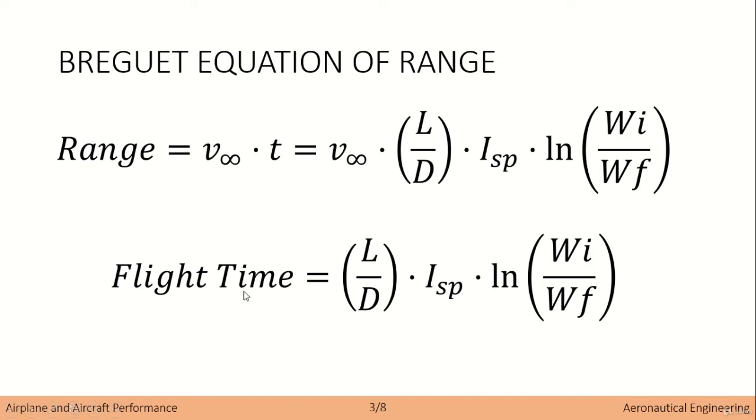Because the flight time can be defined, after some mathematical derivation, as the ratio between the lift and drag, the specific impulse, and this function which is the Napierian logarithm of the relation between the initial mass, initial weight, and final weight of the aircraft.